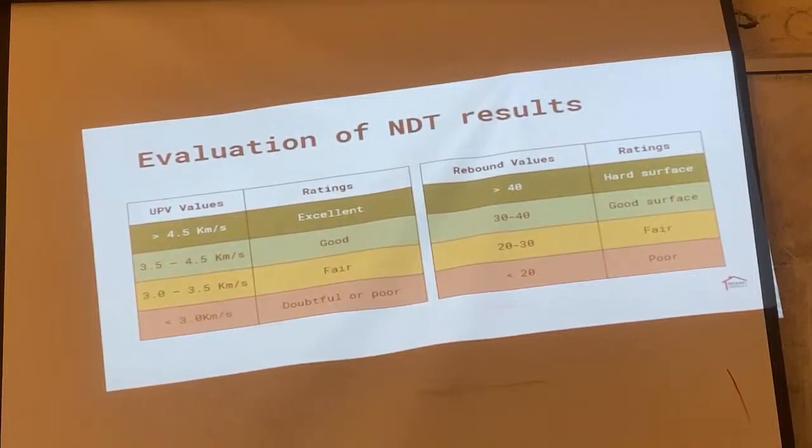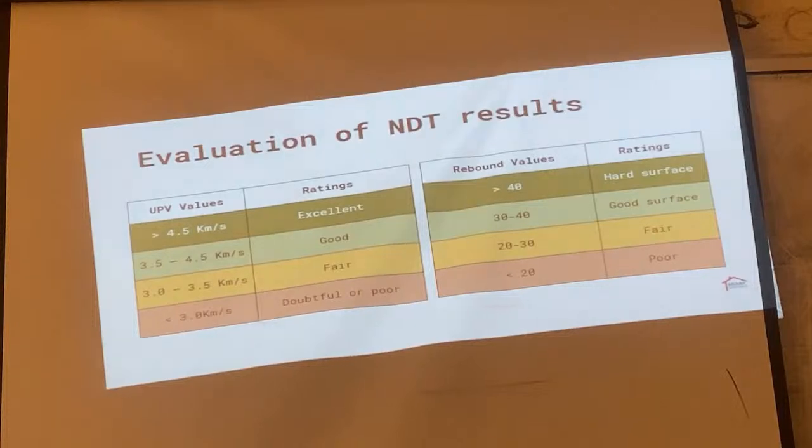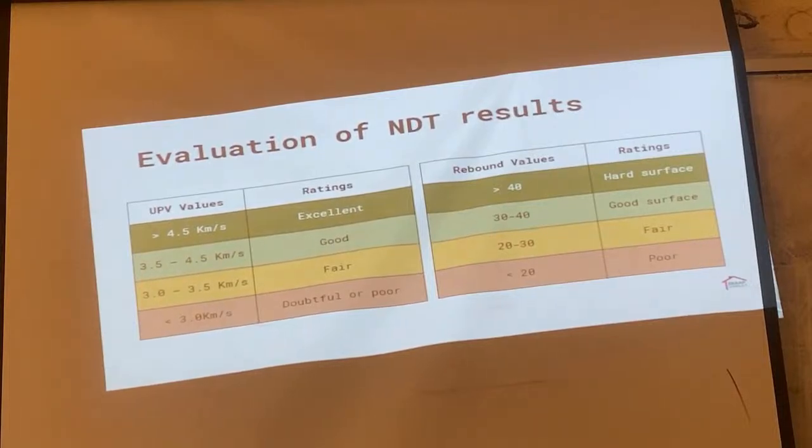The correlation. Okay. So we create a mold cast, 150 by 150. We have different pools. Then let's say we want to achieve grade 25. We use the same mix ratio in our lab. We mix them up, fill them inside those molds, strip those molds down, and cure them for 28 days.